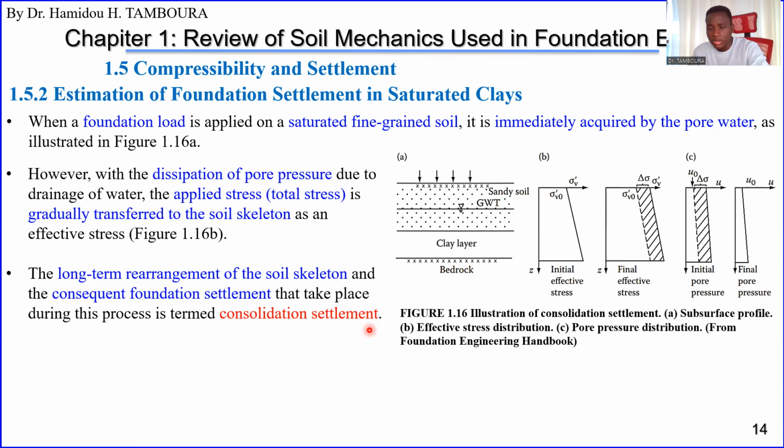Okay, so the water is going, soil particles will undergo some rearrangement, and this will cause a settlement of the saturated clay. So this settlement is what we are calling consolidation settlement. Okay.